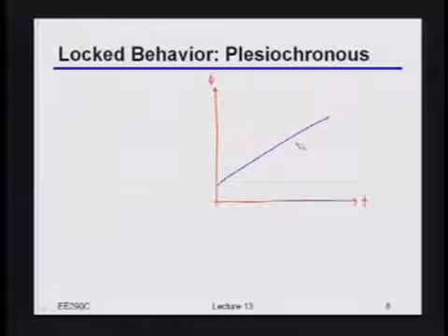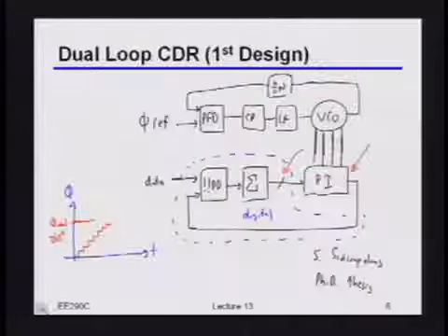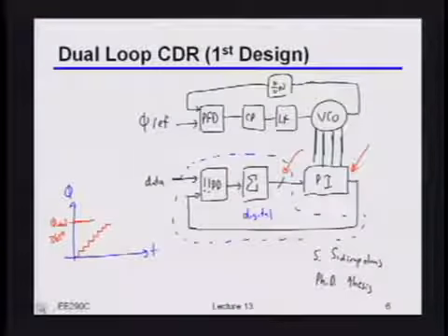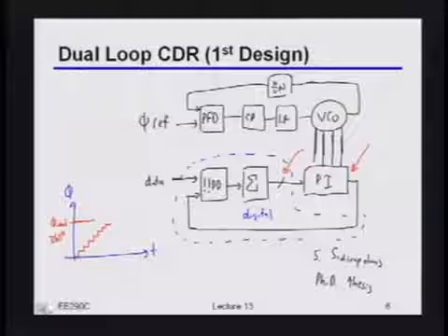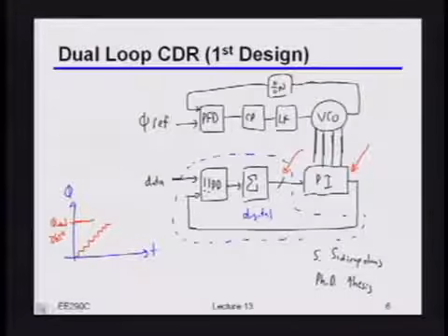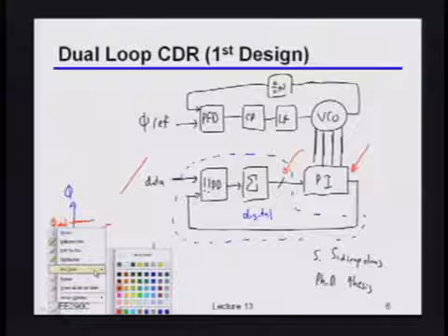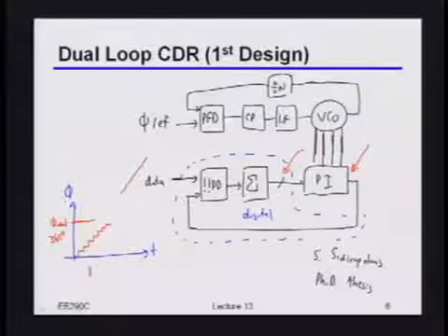phase resolution. And I'll just give you a reminder that this is the CDR that we're talking about. So it's got an infinite number of bits of resolution, but I want to know what happens if you feed a phase ramp into that kind of CDR. So what's going to happen? You'll end up with a static phase offset.